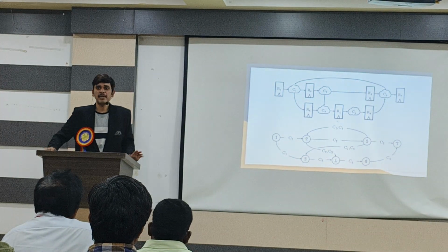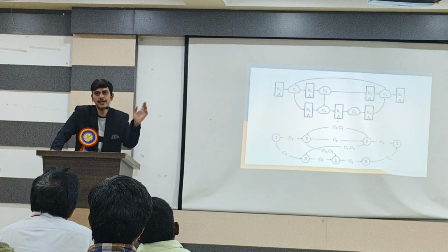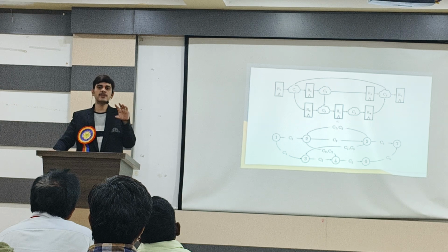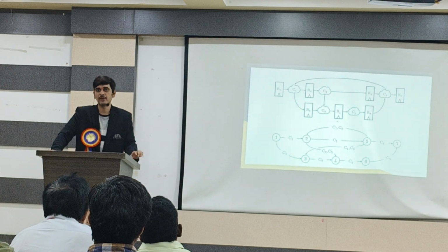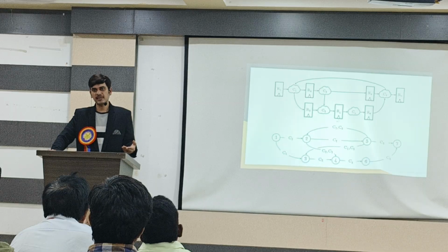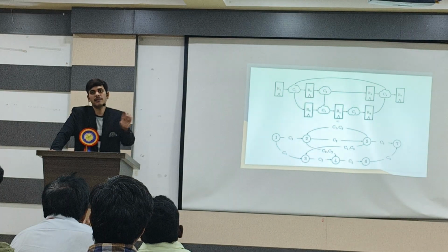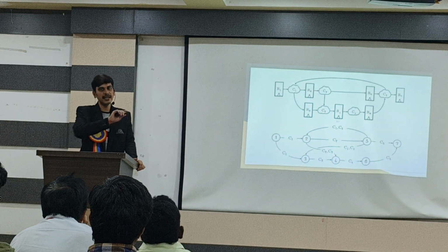So in timing analysis, there are four types of timing paths: input to register, register to register, register to output, and input to output. These are the four types of timing analysis we do. And we have the interface timing. What does interface timing mean? An SoC is not just one block, right? We have an audio block, an image processing block. Every block is individual, but these all interact.